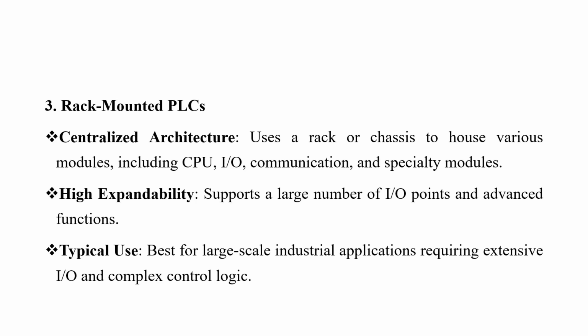Then you have the rack-mounted PLCs. These have a centralized architecture. They use a rack or a chassis to house various modules, including the CPU, the I/O or input-output, the communication protocols or communication channels, and several other specialty modules.